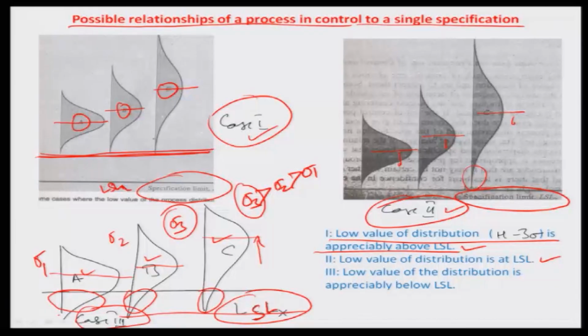So in this particular case, as you can see, greater is the sigma or greater is the process spread, the better it is. Okay. So such cases do exist, where there is always an alignment of the lower side of the limit of rejects and of the particular process, and the moment that goes or starts going outside the lower specification limit, it is always wise to have a wider spread than a smaller spread, as can be seen in this particular example.